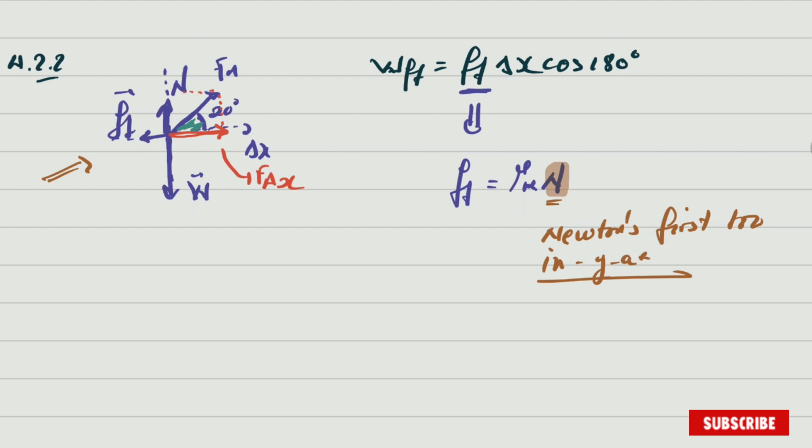If you project it to the y, you have the red one. This is the applied force in the y-axis, which is equal to the applied force multiplied by sin of 20 degrees. Now, what forces do we have in the y-axis? Here are the forces we have in the y-axis, and those are the forces we are going to substitute.